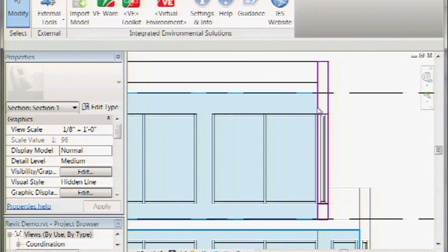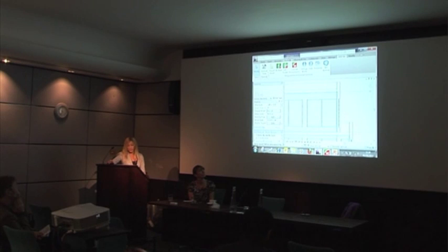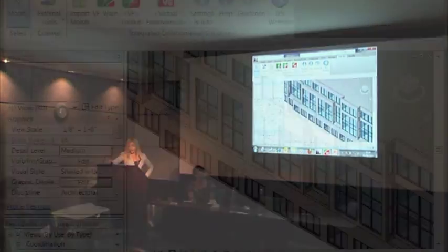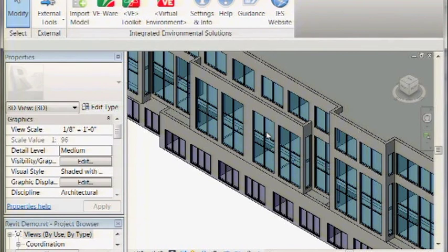Another thing that will cause problems is overlapping your window frames. So if you have a lot of windows along an edge, like this model does, your best bet, like here, for these windows, rather than take a bunch of windows that look similar and layer them together and arrange them so they appear to look the right way, I'm going to want to edit a window family and actually change the window itself so it fits properly, and it's going to come through a lot better.